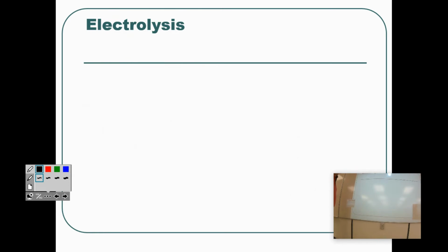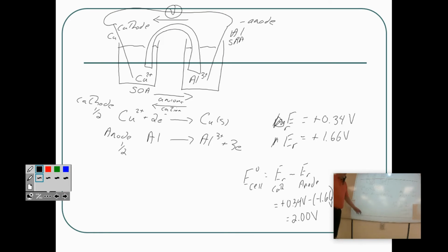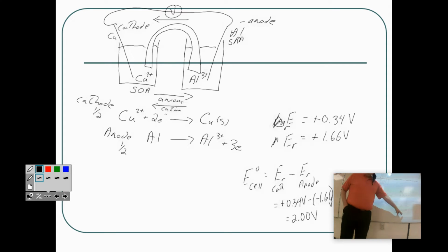Oh, and because we have a 9-volt battery, we have 2 volts per cell, we connect them in series, we need 5 cells, not 4.5, because we can't have half of a cell. That's essentially why it's 5. Even if it was 4.2 cells, we would still bump it up to 5.